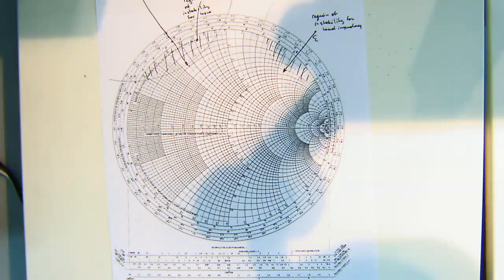Anyway. All right, cool. So now you've worked out stability circles. What we're going to do next on Friday is talk about working out gain circles. We've now got our system that is stable or unconditionally stable. These are the regions in which it's stable. These are all the impedances that give me these gains. If I want this gain, where do I choose? What input and output impedances do I choose so that I achieve that and I still maintain stability? So that's what we'll do next Friday.